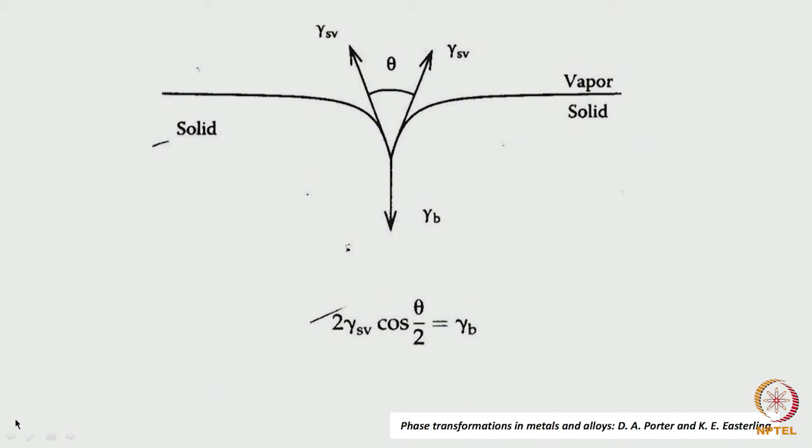But generally, computational calculation of grain boundary energy has lots of difficulties, because there is a discontinuity at the boundary. Atoms are not at equilibrium position across the boundary, because the separation between the atoms doesn't correspond to the equilibrium separation, but could be different from that.